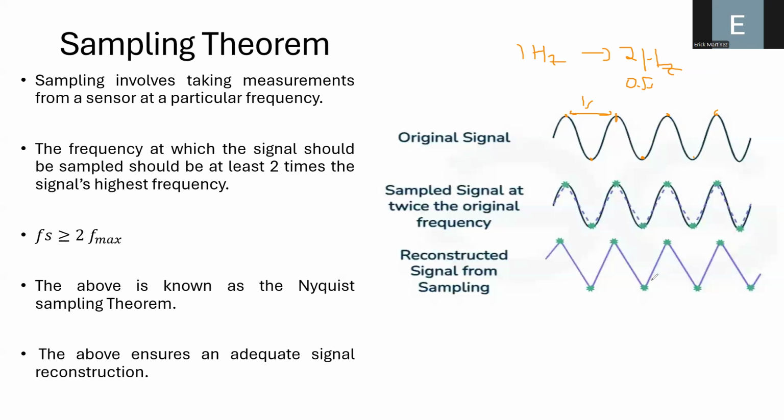Okay, so what I can do is to take more samples. Typically, many computers or data acquisition systems oversample the information in order to have a better reconstruction of the signal. A rule of thumb, to put it in a way, is to sample at least 10 times higher than the maximum frequency of the signal in order to ensure that you have a good interpolation of the dynamics that you want to capture. But it is a rule of thumb, not a reality. It's more like trial and error, seeing if you are reconstructing your information a little bit better.